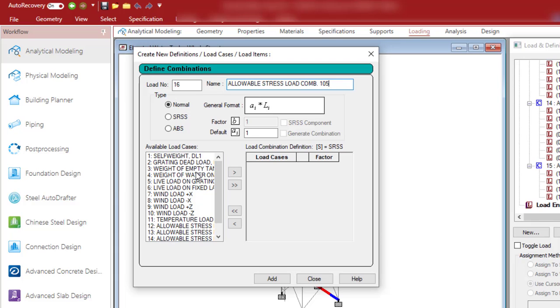When it has the tank full of water, it is more stable like that. But when there is no tank and there is no water, the structure is lighter. So wind effects will actually affect it more. We show when it does not have anything it is carrying. So that's the reason for eliminating the live loads and applying wind from each direction to see how the structure is going to react to whether it can resist it or not at serviceability limit.